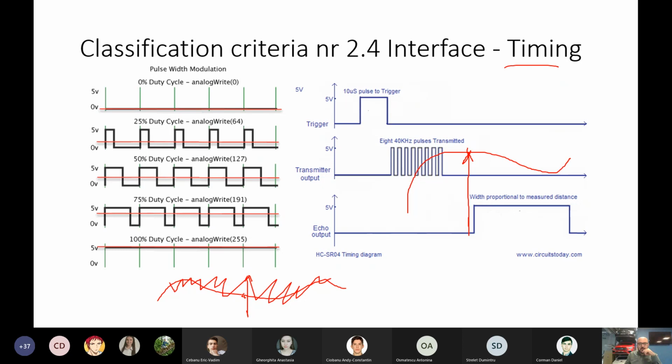We wanted to send this value, but because of the measurement and the influence of the environment, some electromagnetic fields, some phones... Maybe you already heard, when you are driving a car and somebody is calling you, we have some magnetic fields, and you will see some pick, pick, pick on the wire, because there are wires that are influenced by the noises.